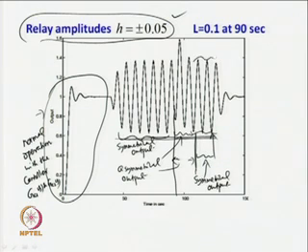So, this is what I mean by the stable limit cycle output. The measurements on the stable limit cycle output will result in correct parameters of the limit cycle output. So, correct values for the peak amplitude and the period, or the frequency, of the limit cycle output can be obtained when the measurements are made from the stable limit cycle output, not from here.